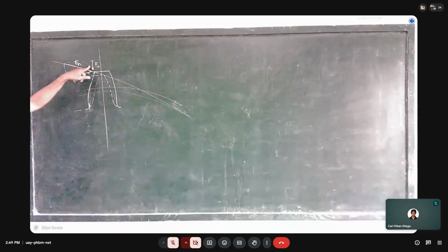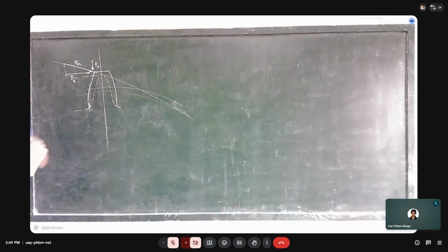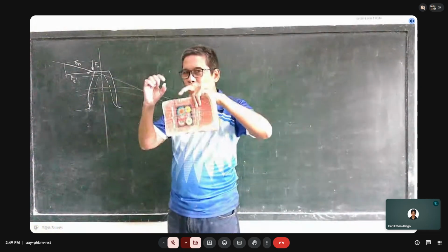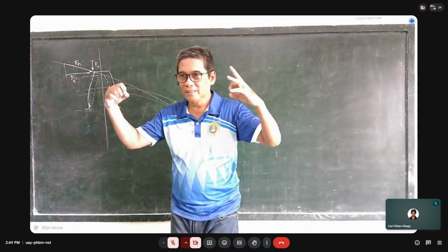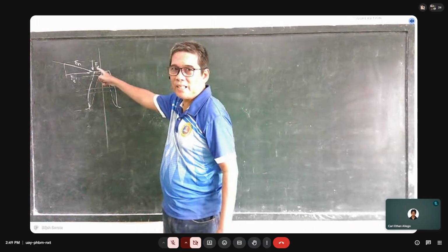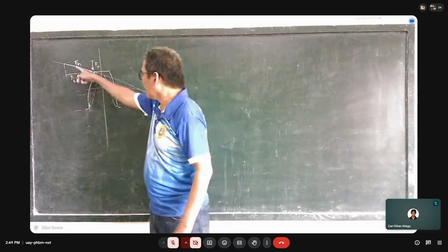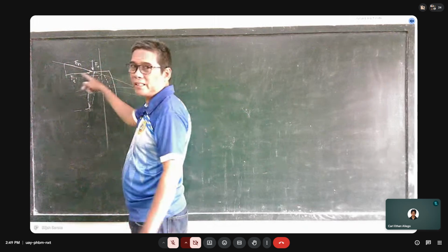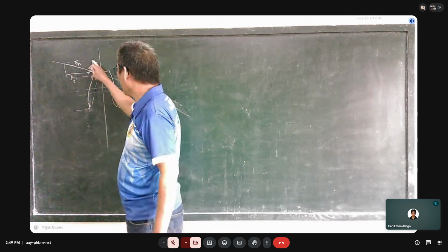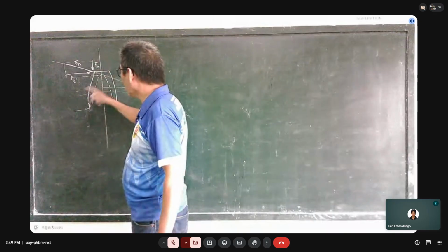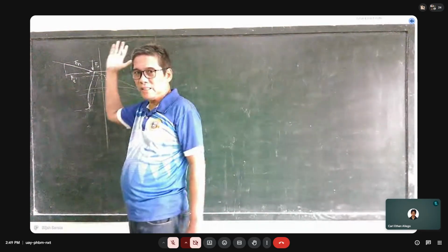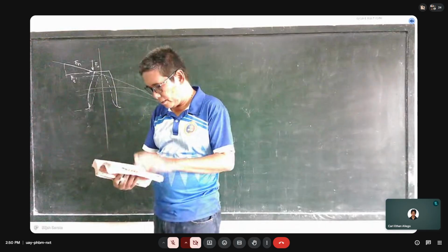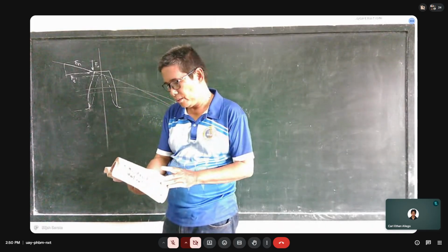For this one, its purpose is to push the gears apart. If you look at the gears, when they are pushed, they will separate because of this radial force, because it is not only the tangential component. But this is the most important part, which is what we want: it makes the gear rotate and drives the gear. So that is the transmitted force.